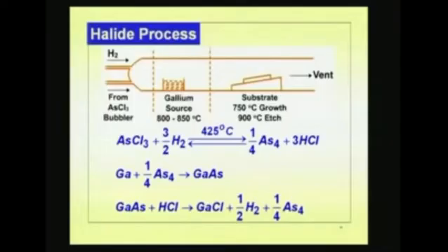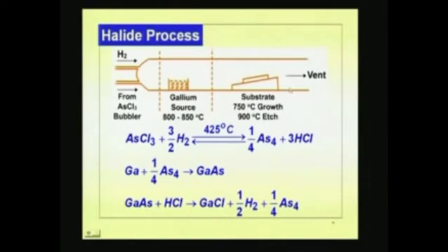During the process, the gallium arsenide substrate is loaded into the boat and the slider well is filled with polycrystalline gallium arsenide melt. Then the slider temperature is lowered at a constant rate, and as the growth temperature is reached, the slider is pushed to bring the melt zone above the substrate.